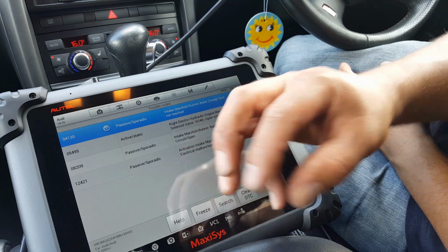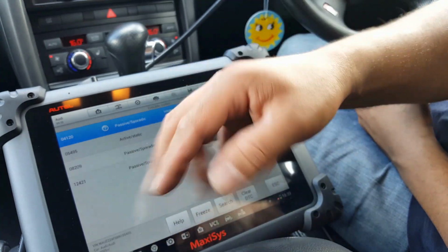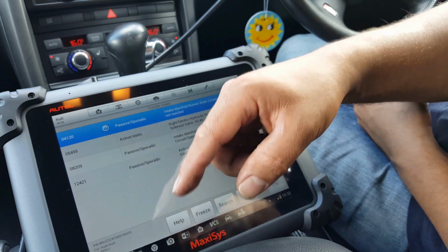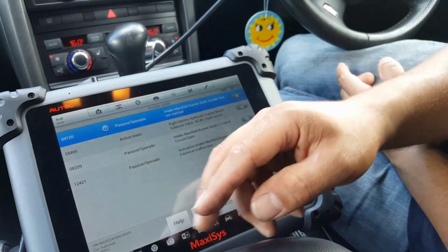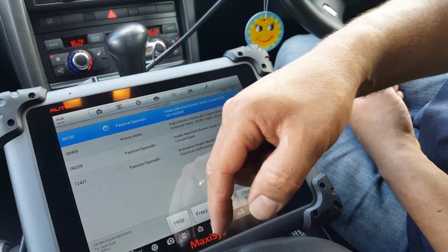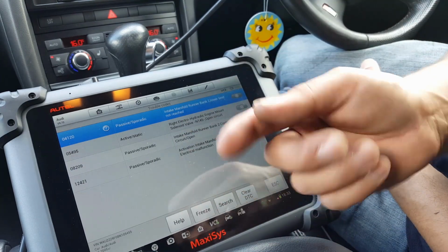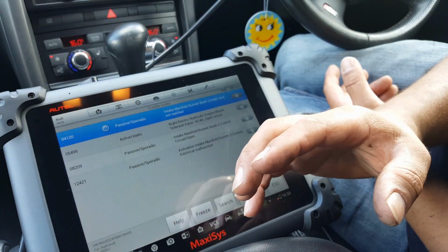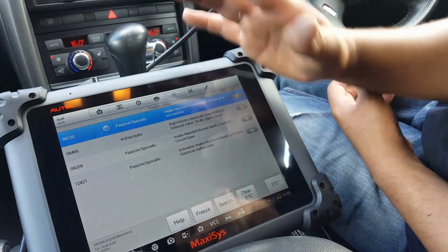But because the shaft and everything at the bottom of the linkage at the manifold was all worn, that allowed the actuator to move over what for the ECU would be the maximum, or minimum, wherever you want to call it. It was going over the lower limit, so it was just moving too far down. So I found a way, which you've seen, with that screw inside, to make it never go below a certain point. And obviously now it's just going to stay. It's not going to move from there.